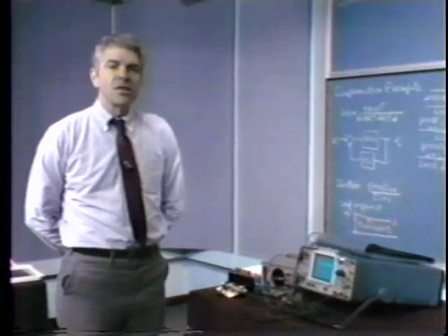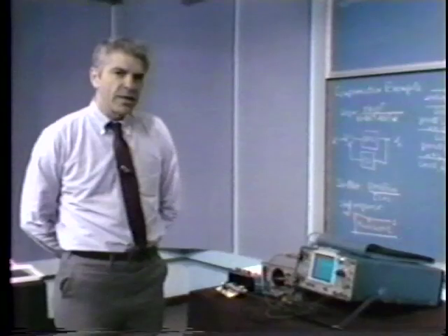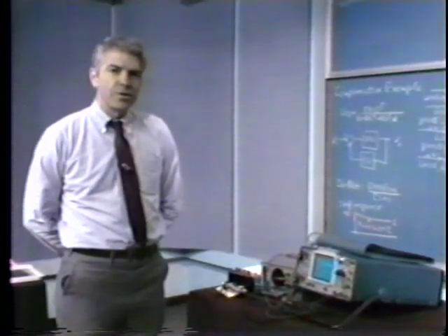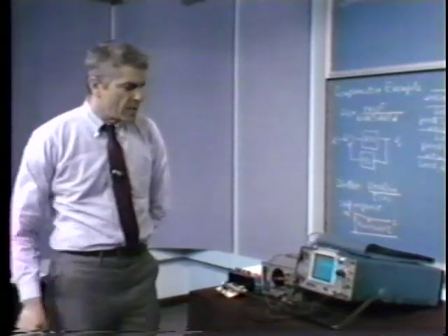Here we have 14 degrees of phase margin, close to 0, at least uncomfortably close from a feedback system point of view. And so we'd anticipate that the ring frequency associated with the step would be somewhere on the order of 4 kilohertz. And we see that.